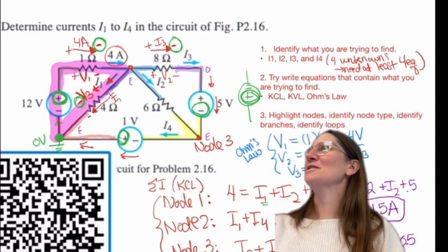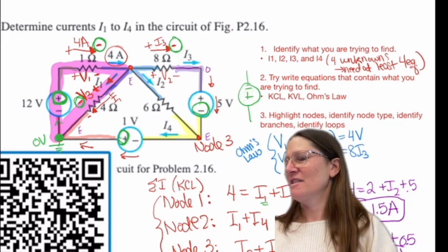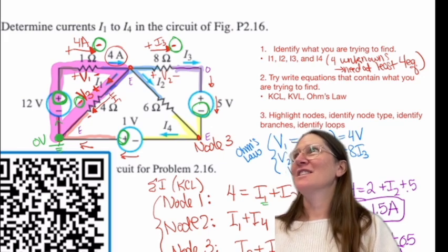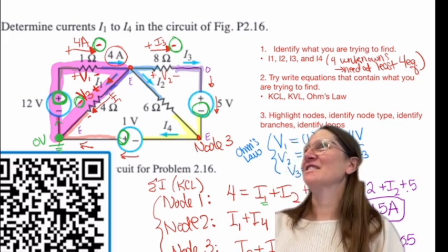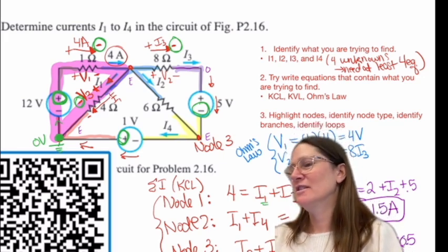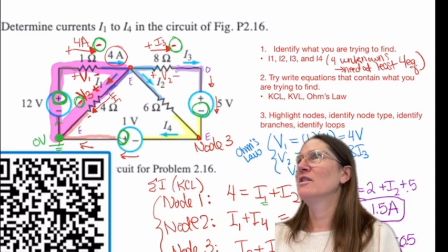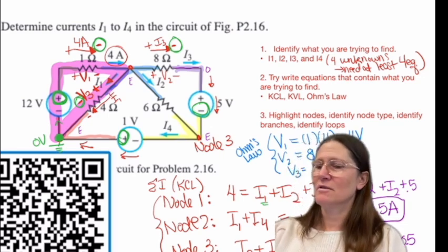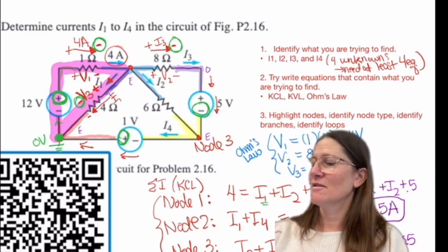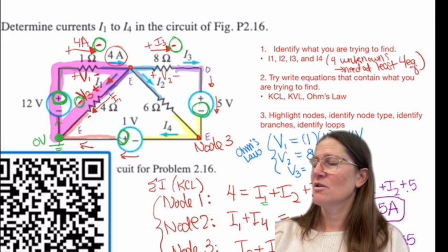All right, in the back first. So I guess to determine whether it adds or subtracts voltage, you just look at the direction in which you're going, and then it's the sign that's exiting. Yes, correct. That's another way of putting it. For determining the polarity of the resistor, it's based on the starting point. If you start at 12, it's going to want to decrease, but if you start at 0 and it rises to 12, it's still going to want to decrease. So you just set as the polarity that will decrease the voltage to whatever the starting point was.